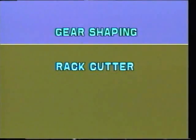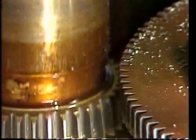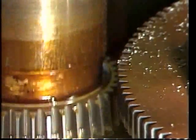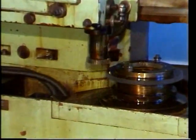Gear shaping can also be carried out by using a pinion cutter. The pinion cutter reciprocates and also revolves in a specific relative motion with the blank. This shaping action generates the involute tooth form, cutting the tooth edges facet by facet. Another process of spur gear generation is by gear hobbing, which produces gears with greater accuracy and higher flexibility.